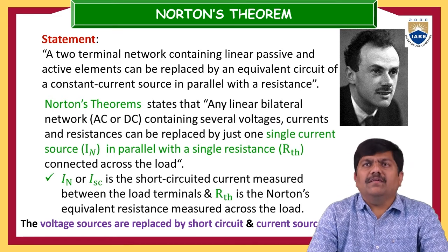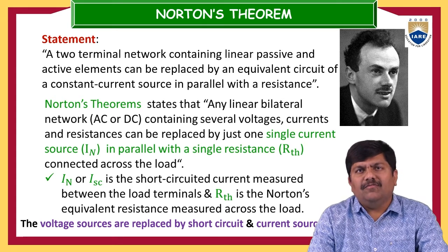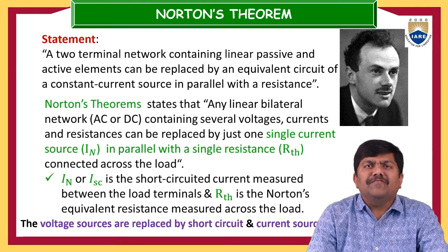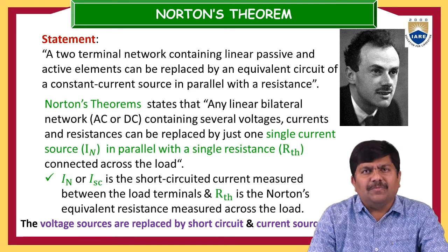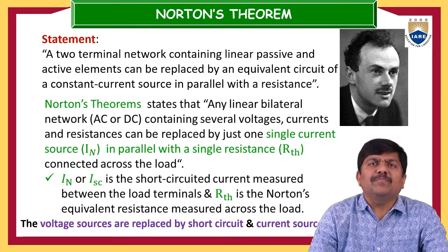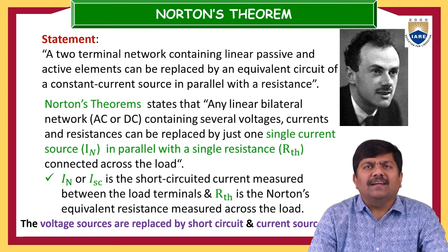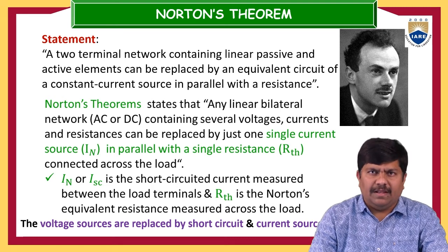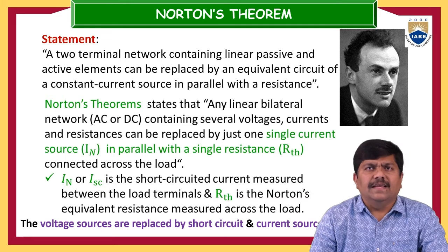Before moving in depth into Norton's Theorem, let us recall what Thevenin's Theorem is, because Thevenin's and Norton's theorems are dual to each other. In Thevenin's Theorem, the load is the particular element in which you are interested. Suppose you want to calculate the current through an X resistor, or the voltage across that X resistor, then that X resistor can be treated as the load.